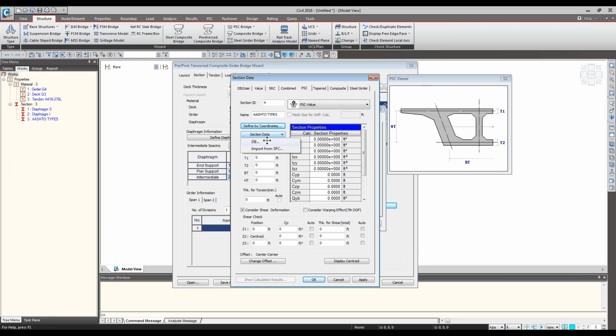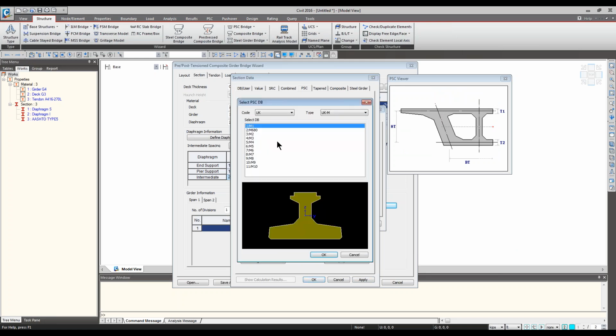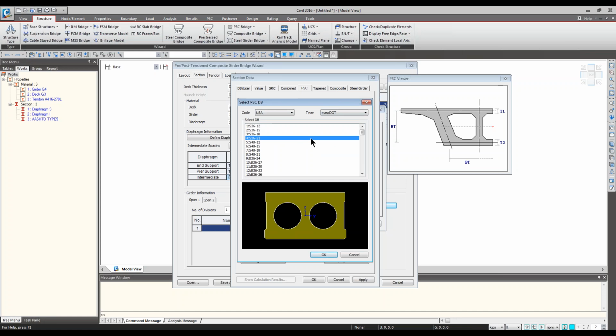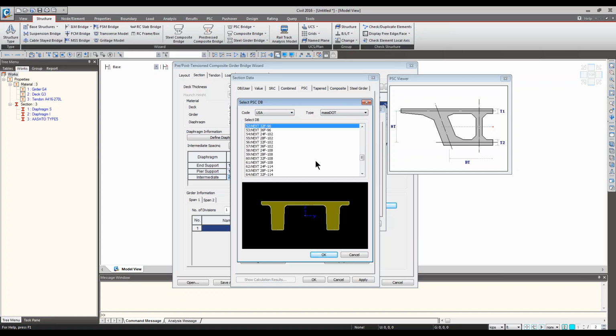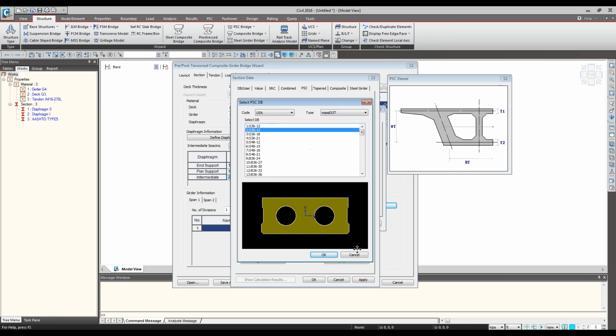You can import the AutoCAD here via the section property calculator tool, or you can simply go to the data again and see over here if we have your database. Massachusetts DOT has quite an extensive section database for prestressed concrete applications. So, as an example, you can bring any of these sections into Midas and use them for this type of application too.